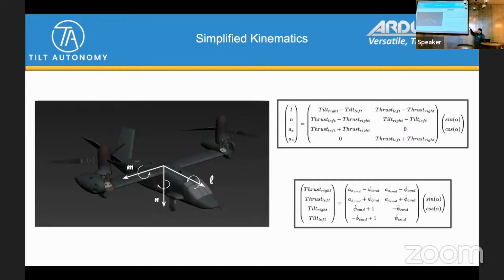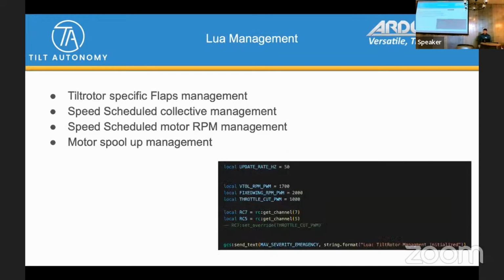They're very basic here, and I don't really highlight in these specific equations things like turning off roll completely when they're fully down. So in this case, to generate roll, you would tilt the tilts differentially. Most likely I won't do that, but it is technically represented in the math there. So you would just have if statements or just drop it to 0 heuristically in the equations that you draw up. But that's the basic kinematics of the vehicle, at least.